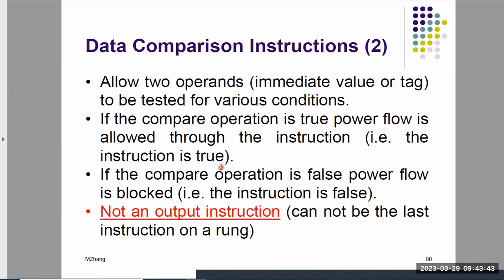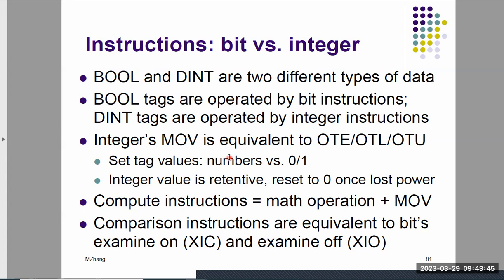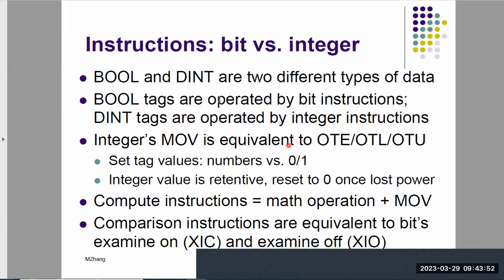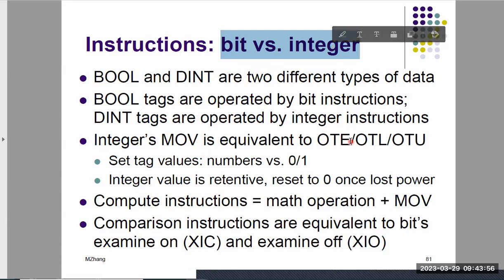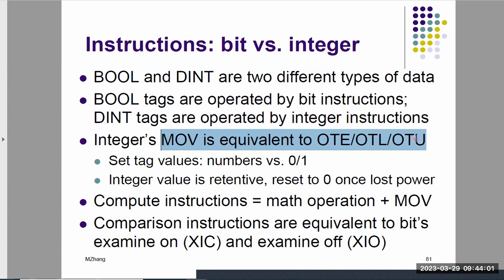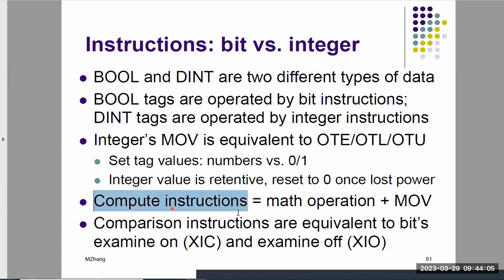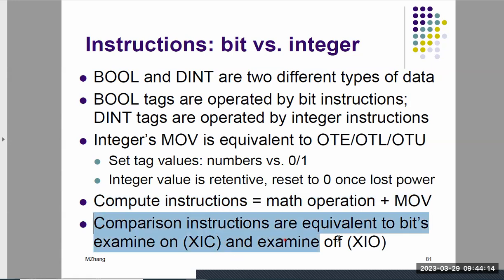Okay, data comparison. Again, like I said, I just want you to have the connections between what you learned before and what you have now, right? So we talk about this: Move is similar to the OTE, OTL. And then this is new, the compare instruction. Compute, sorry, compute is the math plus move. So that's the one I want you to pay attention to, the last one.